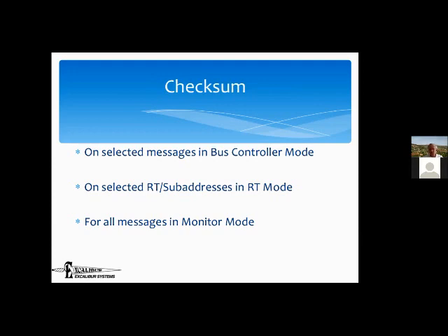Now, not every message needs one. Messages like blow up that town, you would want to have a checksum on. Messages like, how are you feeling today? You know, is your status okay? Are you feeling healthy? That it's important, but it's not important enough to warrant the checksum. So it's not on every single message. The bus controller will decide each time it sends a message whether he wants to have a checksum attached to it. For RT to BC messages, the decision is made by the RT, and it's usually based on particular subaddresses.